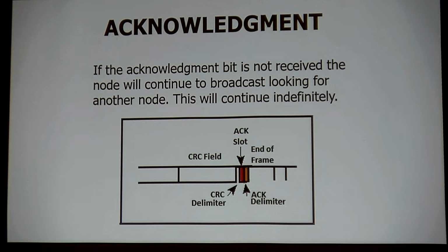So an acknowledgement is just going to go up. And who puts it up? Another module, but not the guy that has control of the bus. He arbitrated, he sent his message, he did his cyclic redundancy check, and now he does not put a bit there. So he stays recessive. Someone else goes dominant, puts a bit there. He says, okay, somebody heard me.